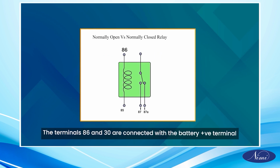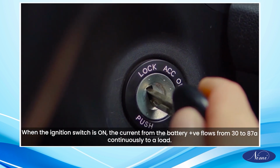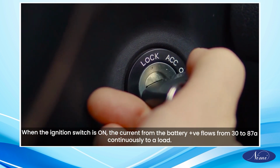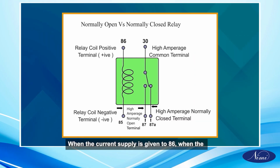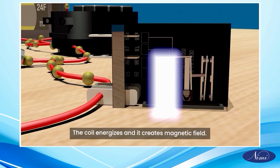The terminals 86 and 30 are connected with a battery positive terminal. When the ignition switch is on, the current from the battery positive flows from 30 to 87A continuously to a load. When the current supply is given to 86, then the current flows through the coil. The coil energizes and it creates magnetic field.